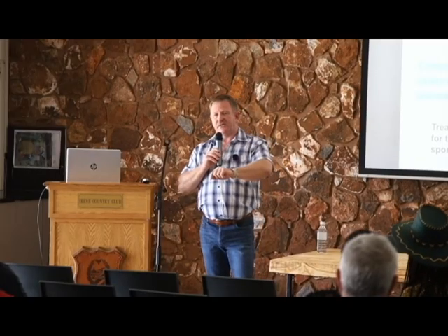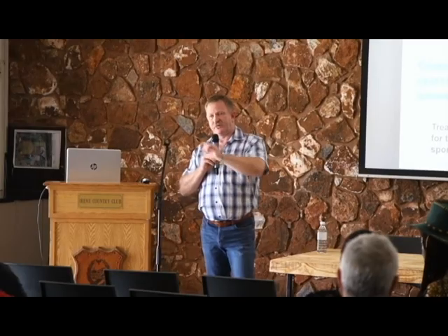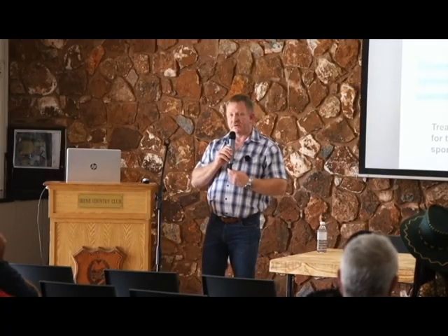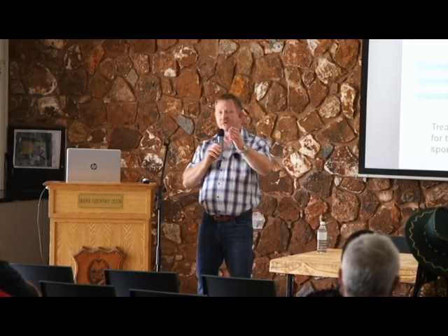Whatever dies, too bad. The garden was looking better using only the grey water with aeration than it was using 18 kiloliters of grey water plus 12 kiloliters of municipal water. So you condition your water, you improve the quality of the water, you turn your ammonia into nitrates, and your garden will look significantly better with even less water that you put on there. So it's very, very important to do that investment and treat your grey water before you use it for irrigation. If you want to know how, you can put your name down there and we'll get back to you later.